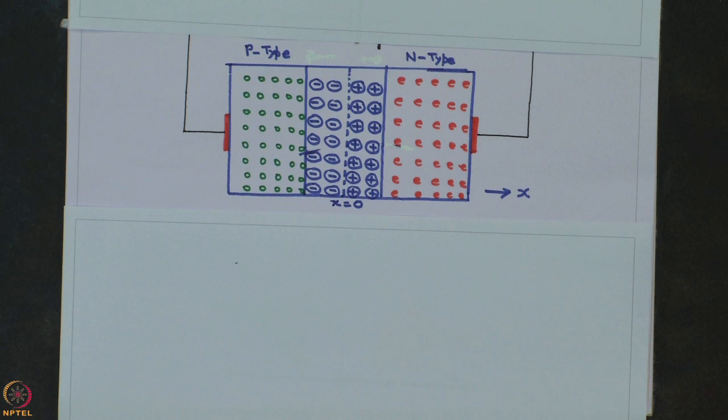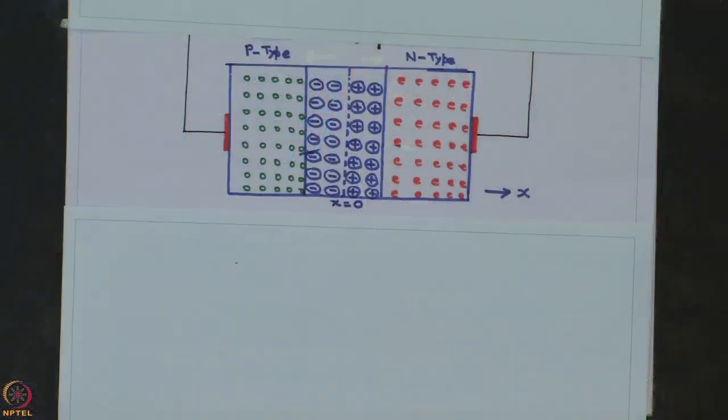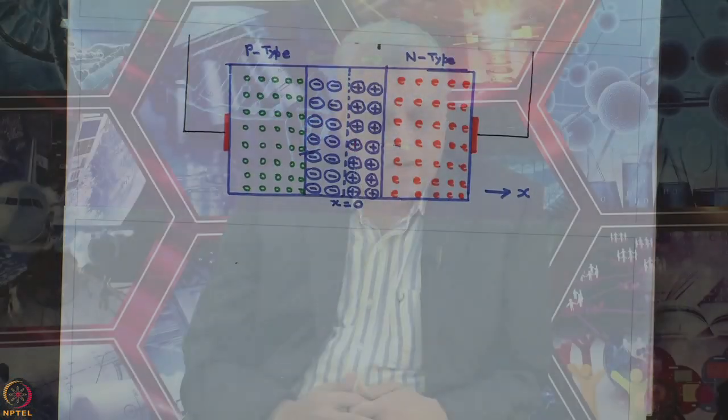The Pn junctions are used as diodes which do not have a control terminal. Now, if you remember in my earlier lectures, we have grouped diodes under the category of type 1 switches. Now, they turn on and turn off depending upon the magnitude and the polarity of the voltage that gets applied across them by the circuit in which they are connected.